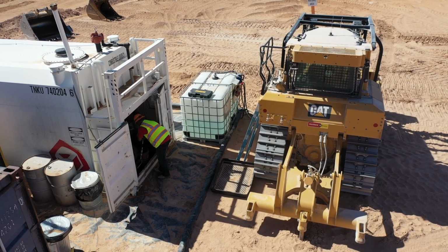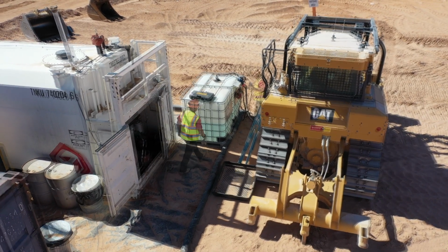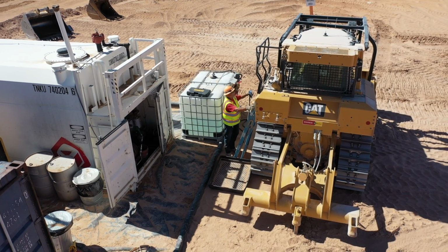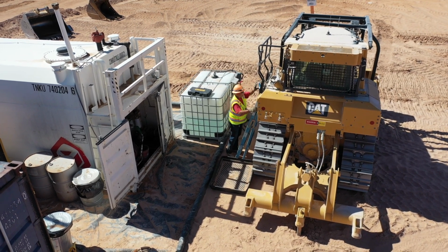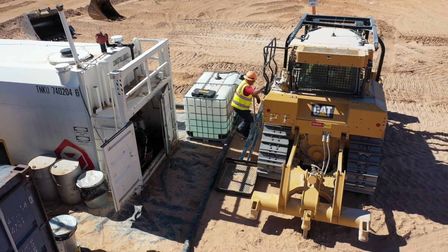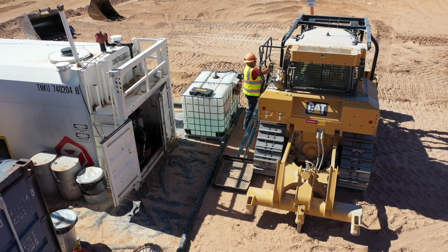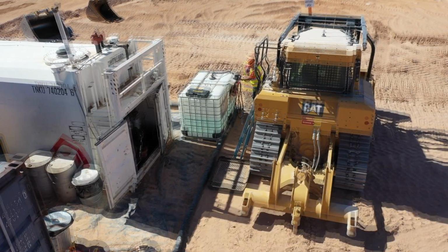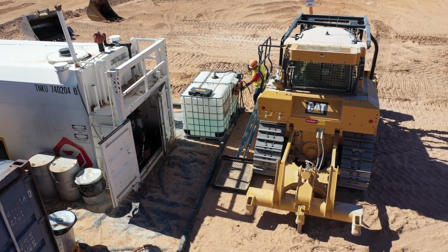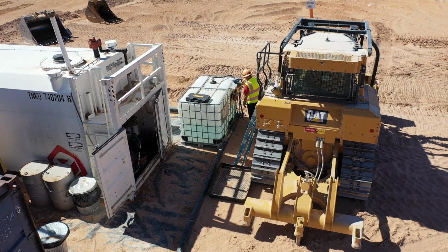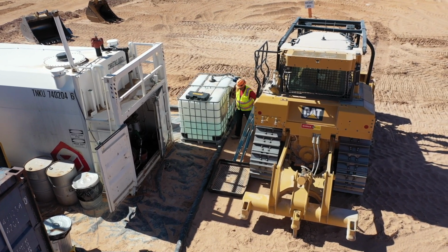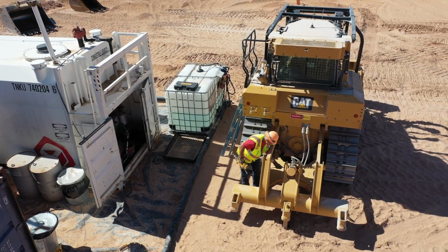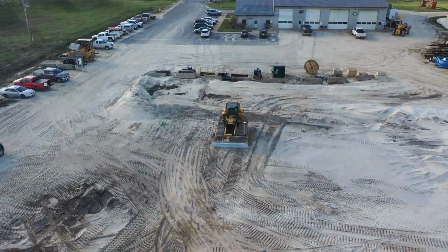If equipment breaks causing contamination to the soil and a spill occurs, contain the spill by use of spill kits or mats and document on the HSEF 14 form and report to supervisor and maintenance. Beware of spills and splashback. Return the fuel hose to its proper storage position when fueling is completed. Grease your machine only after refueling. Do not refuel and grease simultaneously as a fuel spill may occur.